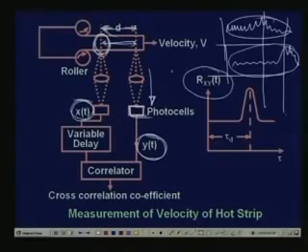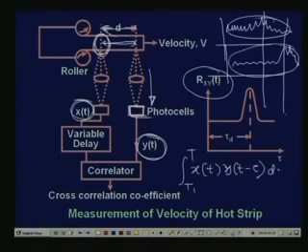So now we are going to determine precisely that. If you have two roughly time shifted signals, they may be slightly different, then there is a technique of correlation. So if we compute, let us say, the integral from t1 to t2 of x(t) y(t minus tau) dt.